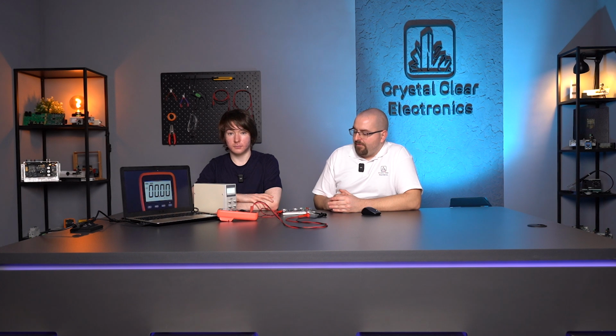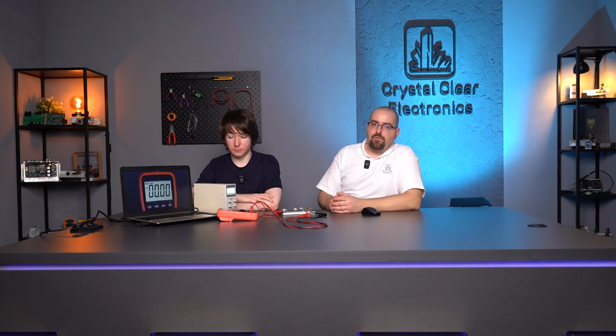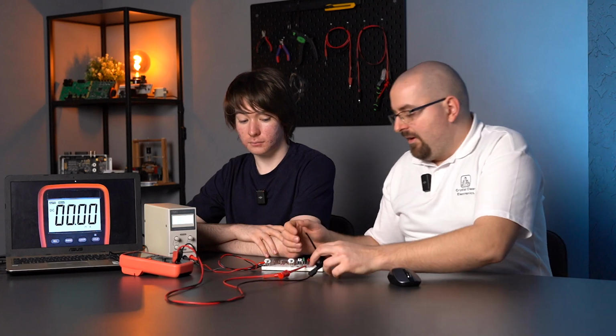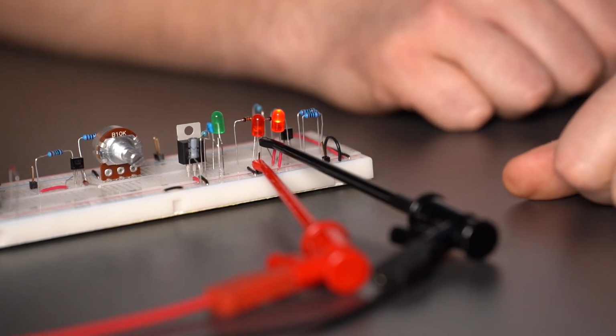The lab power supply provides 12 volts. With this multimeter, we will measure the current drawn by the circuit in current measurement mode. More precisely, the load current flowing through the LED. You can see this here on the laptop screen. The LED hasn't lit yet because we have to connect the current meter to the circuit. I'll do that now. And then, you can see about 15 milliamps as we planned.